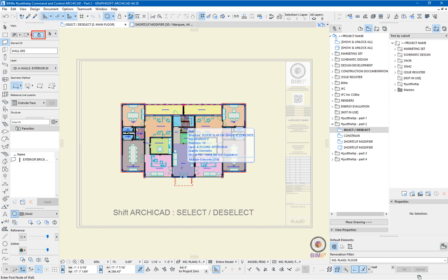It's doing this because the quick select function is active. This detects elements under the mouse and quickly selects. However, that's only one part of the story. So select, hold down Shift, click the mouse, that selects the slab. Fair enough. If I escape to deselect, I can move the mouse around and you'll see it wants to pick up different things and it highlights what those things are.